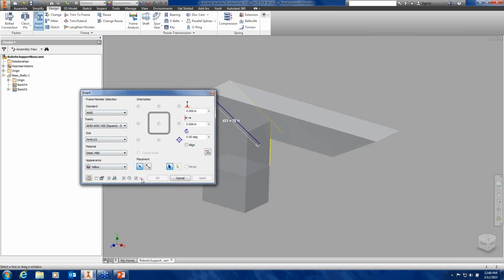You've got buttons running across the bottom. The main thing I recommend is prompt for file name. Turn that off. Let Inventor name it whatever it wants. And then the second one there is for the storage and how it's going to go in and be stored exactly inside of the folder structure of the project that you're in. And a few other buttons down there too as far as how you're going to select your